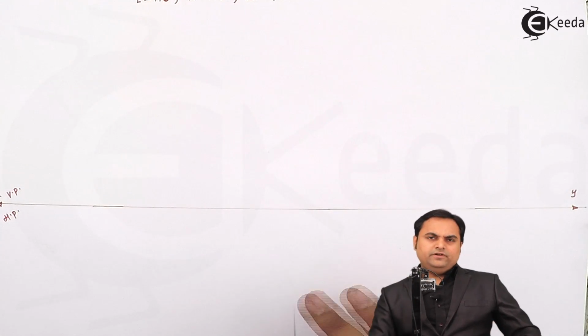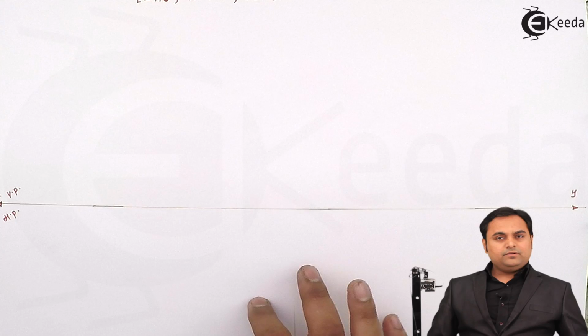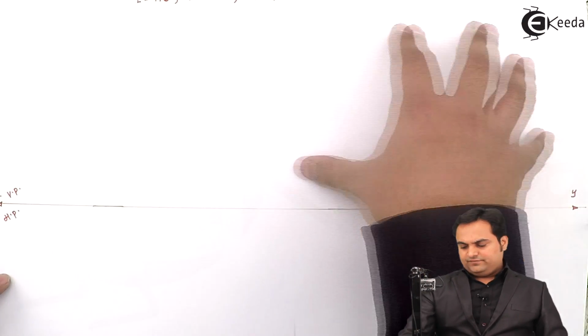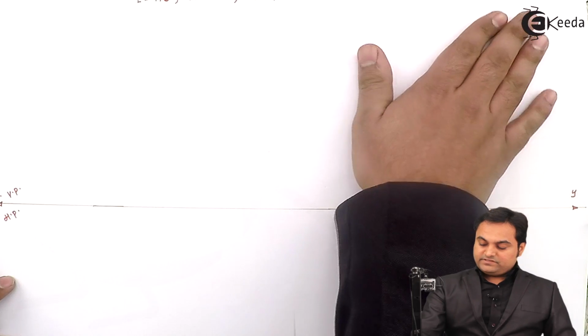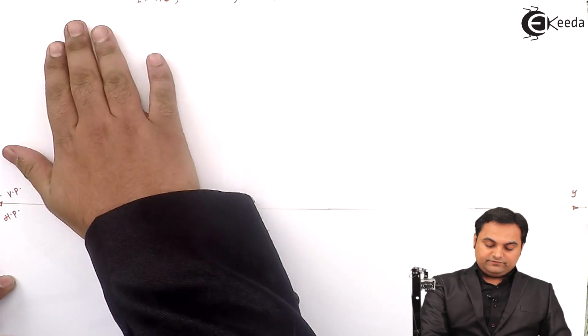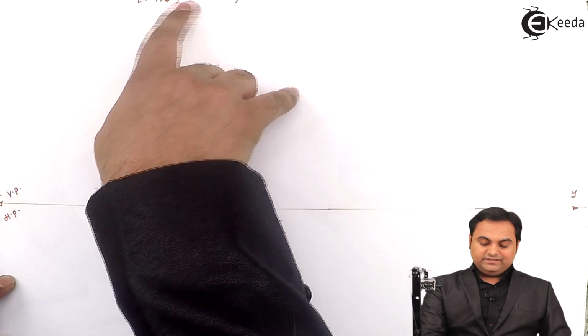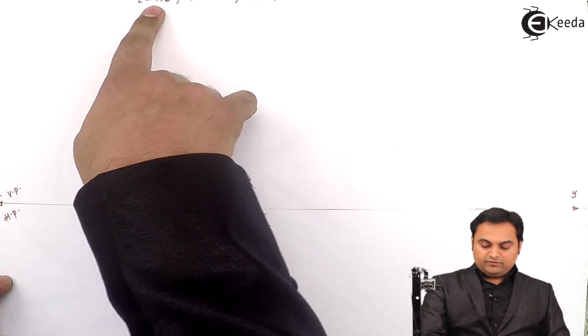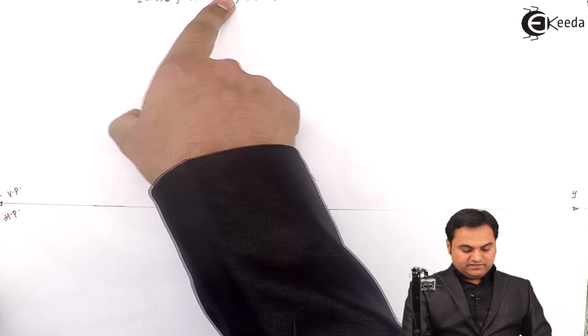Here, as we have to draw left hand side view, and by first angle method of projection, left hand side view should be drawn on right hand side, that is in VP, and it means if the side view is on right, front view should be on left, and in the front the length and height are visible. So I'll draw a square here of length 116, and even the height is same.